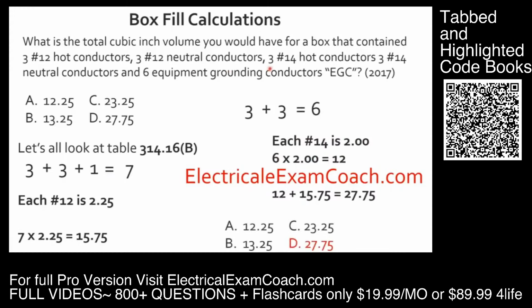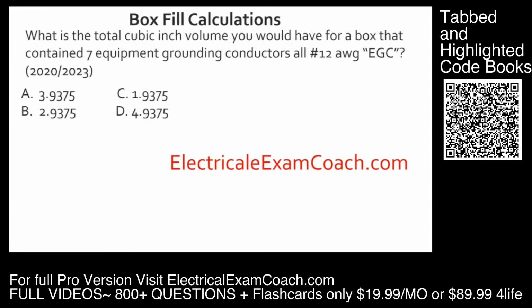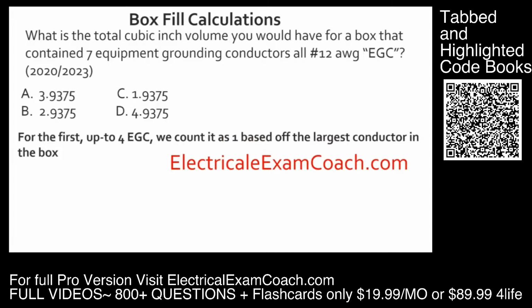Now let's move on to the 2020 and the 2023. What is the total cubic inch volume you would have for a box that contained 7 equipment grounding conductors, all of the 12-gauge persuasion in the 2020 and the 2023? I left out all other conductors because you're going to use the same rules in that after you do this calculation, you group it with whatever the largest conductor is in the box, like you learned previously. What we're going to do is count the first 4 and count it as 1, and then a 1/4 inch increase for each one past 4.